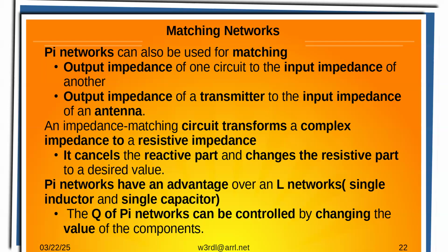Well, excuse me, 50, because you got the 75 ohm point. It's a lot easier to do on the Smith chart when you know how to use it, but there's formulas that you can find online or in a book that do the same thing. But that's essentially what they're doing, is figuring out where that crossover on the real axis would be, which means you've canceled out the reactances, but you have an effective R. So you've actually changed the R value and eliminated the reactance.